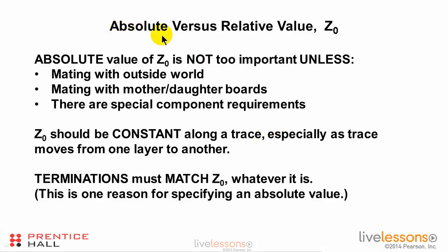Now we can get to this question of the absolute value versus a relative value of Z0. And I will argue the absolute value of Z0 is not important. You can pick whatever value you want. The absolute value is not important unless you're going to mate with the outside world, in which case you now have to match what happens at the mating point between your design and the outside world.